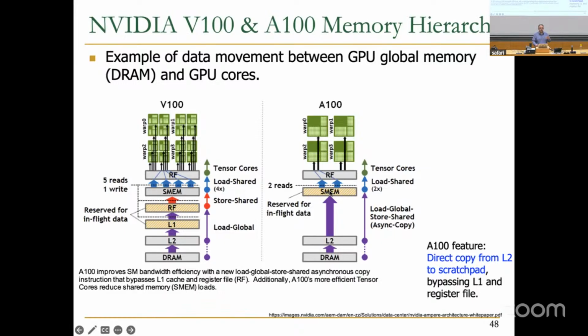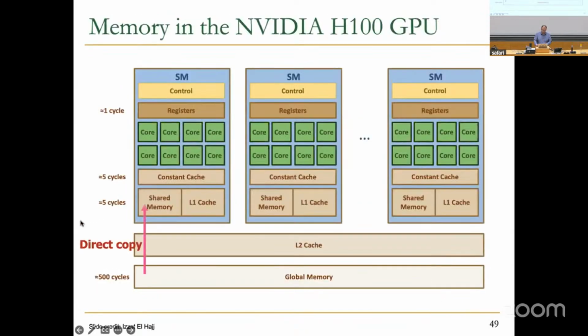So that's also one of the design decisions that the designer and architect should make, and then software should be able to support that. And that's the whole system that they provide in order to support this idea. Another basic improvement in Hopper H100 is that they provide this direct copy from the global memory, which is the GPU device memory, to the shared memory, for example. Also, they show that shared memories can communicate data together. That's another support that they provided.